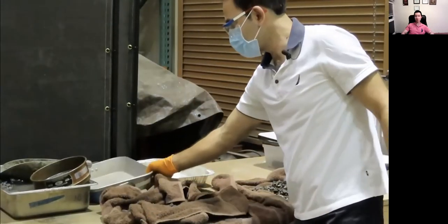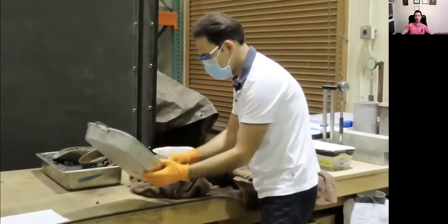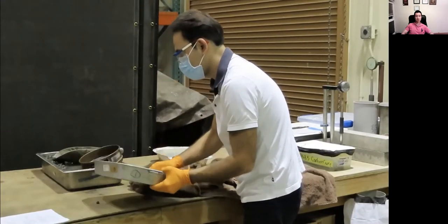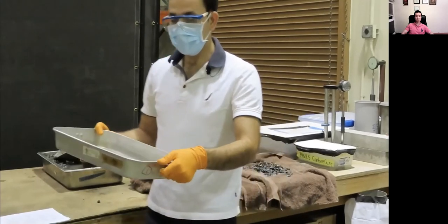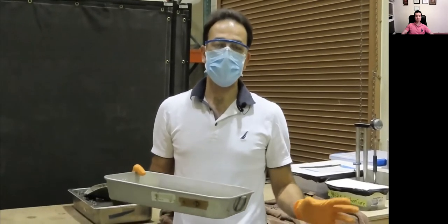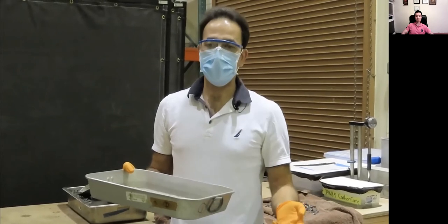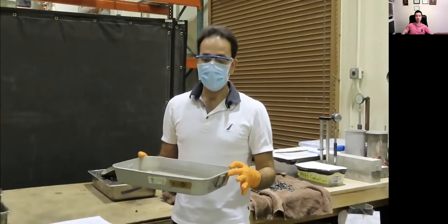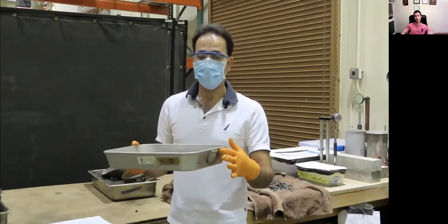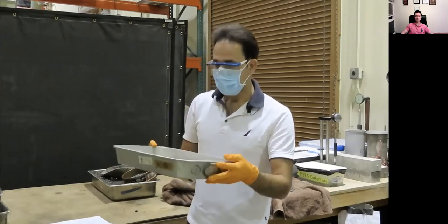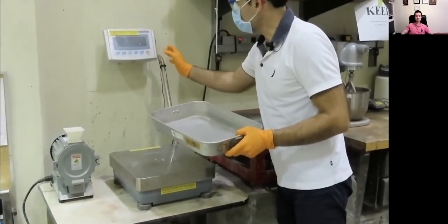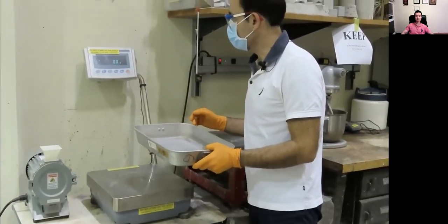I need a container to weigh my sample, so it's a little bit wet. Make sure that I don't have excessive water in the container, and write down the number for the container, because after the experiment today I need to put all the sample in the oven and then come back tomorrow after 24 hours. And what I'm going to do is weigh my aggregate and container together. I need to subtract the number that I've got today. So make sure that you have the number for your containers.